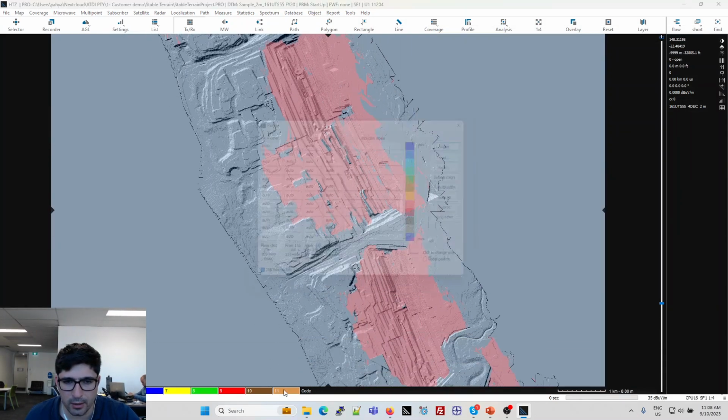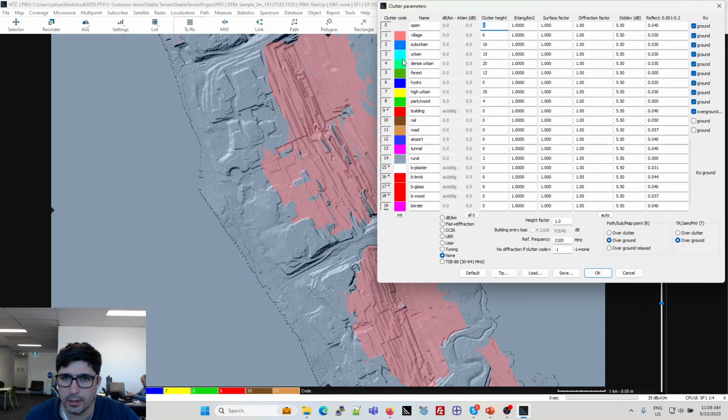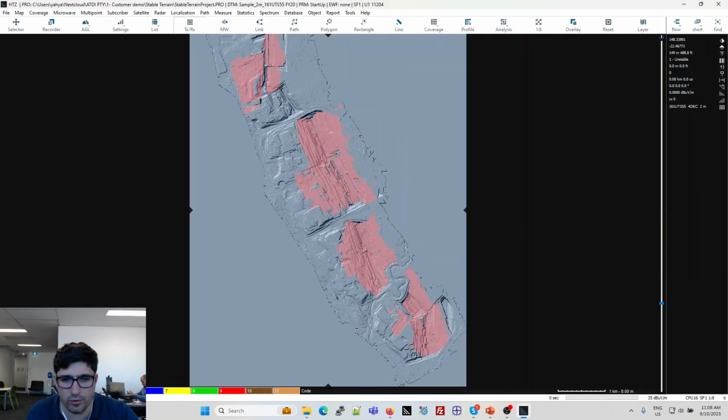So that clutter code number 1, so you can press here in the barcode, and here we can call this number 1. Here 0 is stable, and here is unstable. Okay, so these are the clutters I'm using right now. Don't worry about the rest, and make sure here the clutter height is set to 0. You don't want to create artificial fake height. Okay, so I'm going to put all this to zeros, 0, and yeah, both of them 0, and voila.